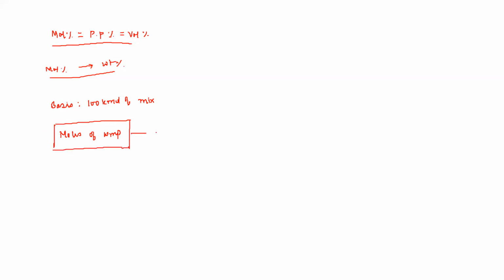Yesterday, I taught you a very important concept as to how to convert mole percent to weight percent. So in order to convert mole percent to weight percent, I told you, first of all, you need to take basis as 100 kilomole of your mixture. Based on that, you would get moles of individual components. Using moles of those individual components, you would be able to get masses of individual components by multiplying moles with molecular weight.